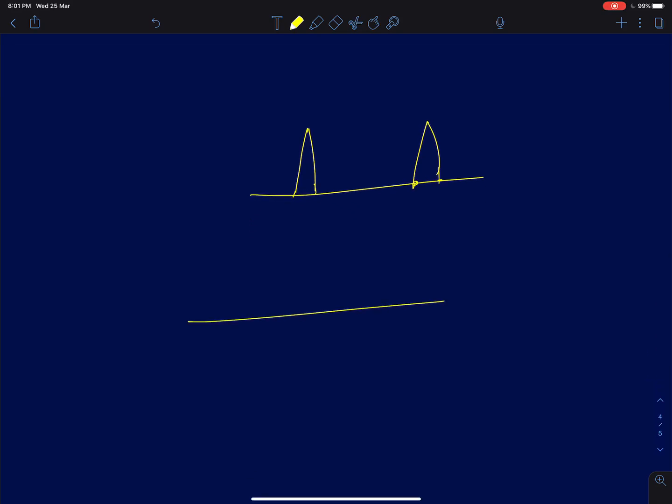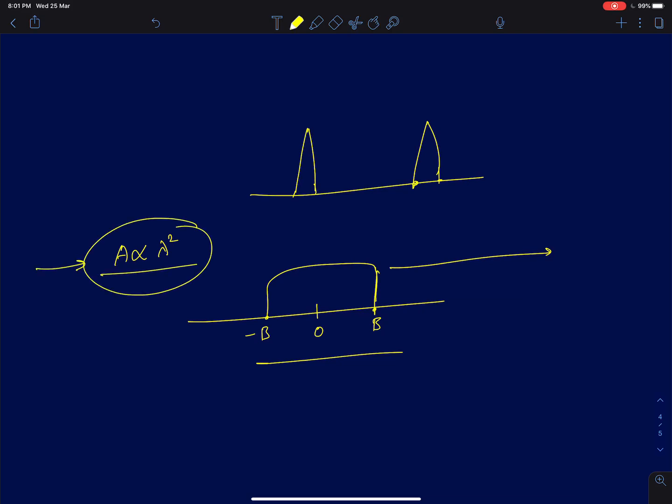For example, let's say we didn't do wireless modulation. If you recall from the previous introductory lectures on amplitude modulation and frequency modulation, we said the aim of wireless communication is that you have low frequency data with a bandwidth centered around the origin, around DC or low frequencies. Now you want to transmit this wirelessly over a long distance. We said that the area of the antenna is proportional to the wavelength squared. For efficient radiation, the dimension should be in the order of the wavelength of the electromagnetic wave. A low frequency signal will have a large wavelength, which means the dimensions of the antenna become unreasonably large. That is why we said we go for modulation.